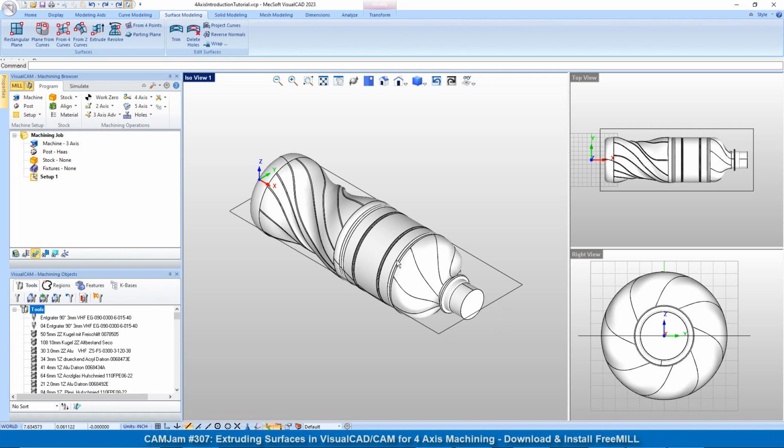And to do that, you need to have some part geometry that extends out past the part on each end, which connects to the uncut stock material. So what we're going to do is add a circular surface running through this part file out past this perimeter right here, which is our roughing perimeter.